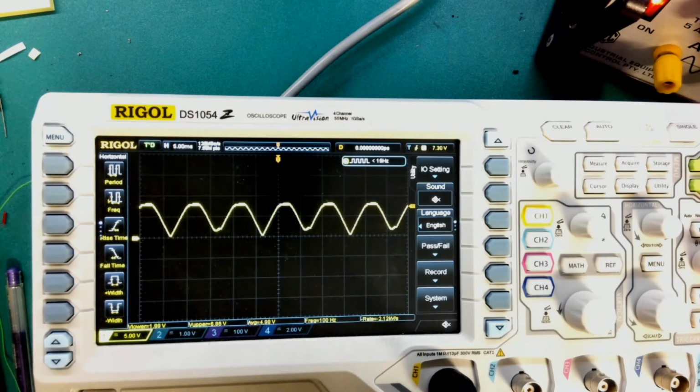We can see that that DC is fluctuating wildly. In fact, it's fluctuating at something like, I don't know, what's that? 100 Hertz. Here we've got our waveform and we can see down here that those little squares are measured in units of 5 volts. So that's 0, 5, 10 volts. So this is somewhere between that. So something about 7 volts.